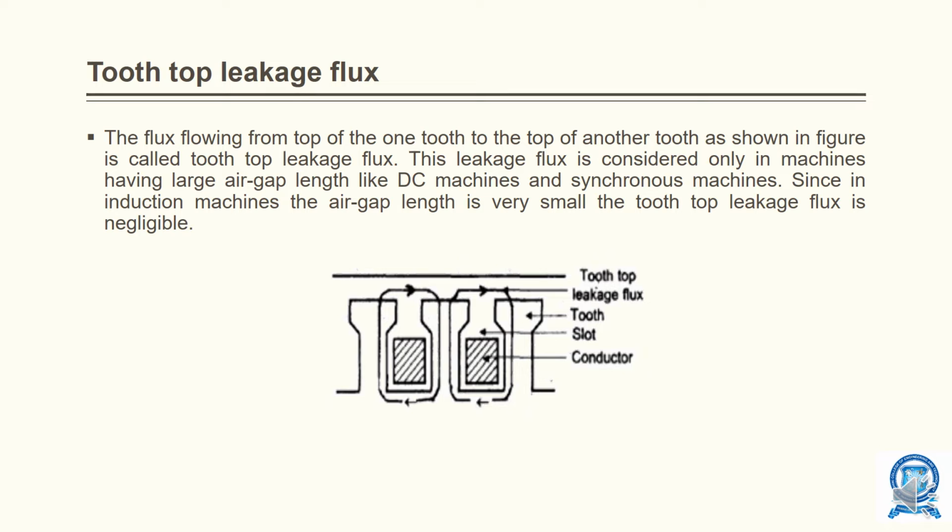Tooth top leakage flux. The flux flowing from the top of one tooth to the top of another tooth, as shown in the figure, is called tooth top leakage flux. This flux is considered only in machines having large air gap length, like DC machines and synchronous machines. Since in an induction machine the air gap length is very small, the tooth top leakage flux is negligible.